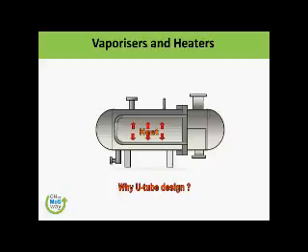Here you see the tubes are more or less a precise U-tube. But when the liquid enters from here, it will be roughly minus 161, and when it leaves, it will be nearly plus 10, plus 50, plus 80, whatever temperature. So you can imagine this line will be trying to contract or go shorter, and this line is going to be expanding.